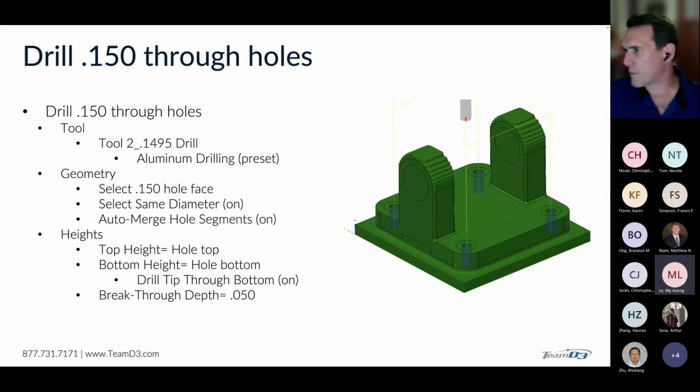There was a question that I'd missed about whether you select any hole. In this case, you can use that option to auto select the other holes, as long as it's one of the smaller diameter, the lower drilled holes down at the bottom and not the counterbore. The answer would be yes.